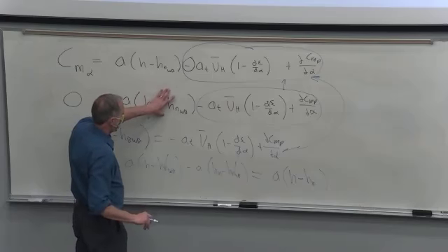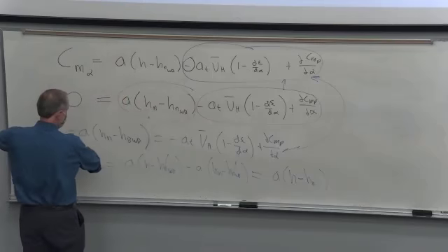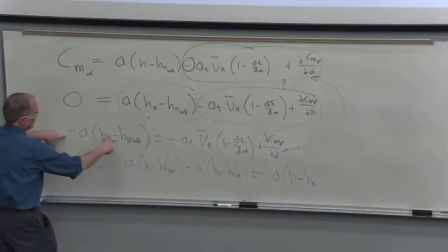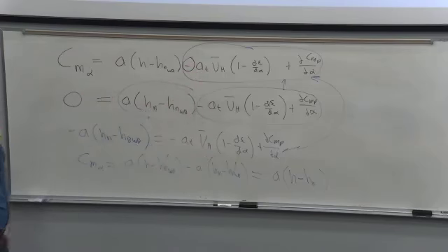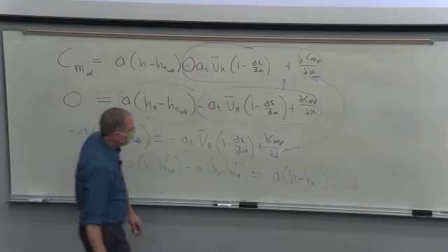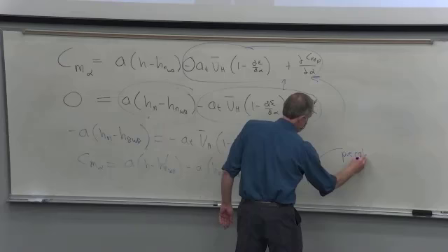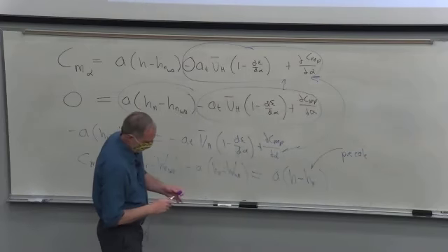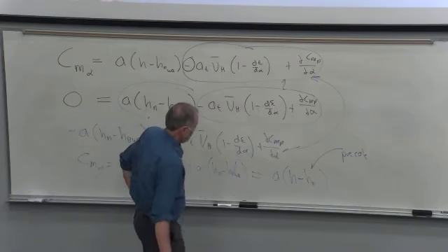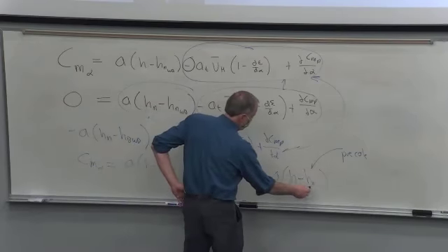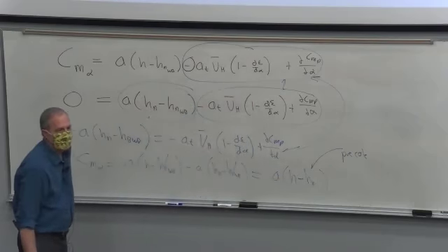So I just took this thing, I solved by moving this over to that side, get the minus sign, and then that whole thing substitutes up for there, and we get a nice, easy formula for CM alpha, if you've already pre-calculated this. And really, this formula is just saying, well, if the neutral point is behind the CG, then you get a negative sign. We'll talk more about that next time.